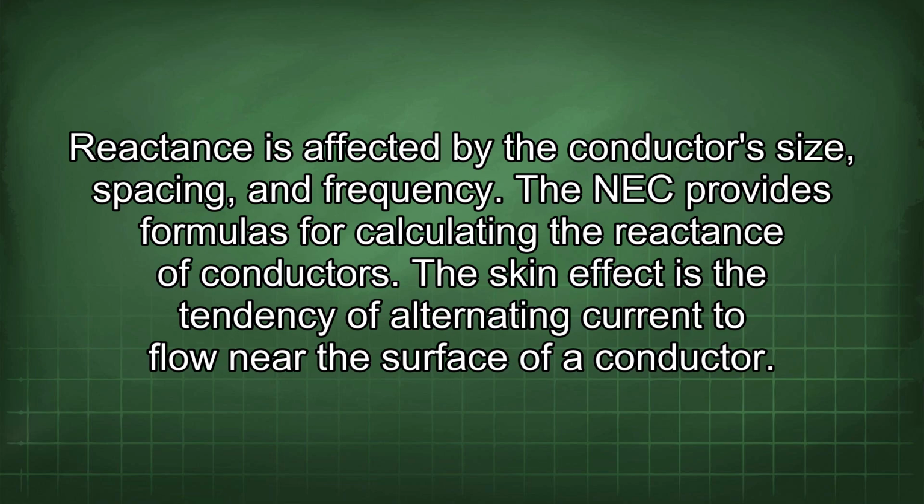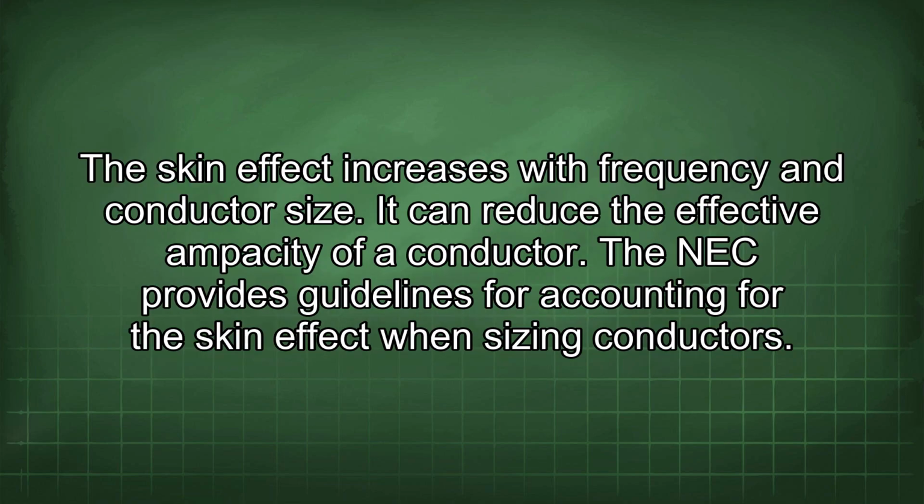The skin effect is the tendency of alternating current to flow near the surface of a conductor. The skin effect increases with frequency and conductor size. It can reduce the effective ampacity of a conductor. The NEC provides guidelines for accounting for the skin effect when sizing conductors.